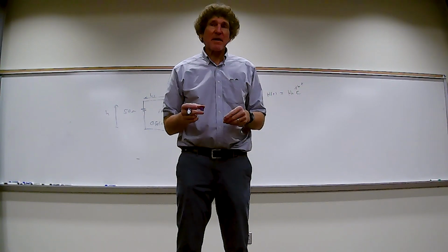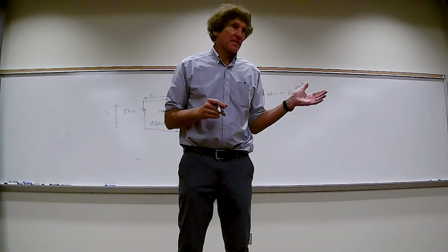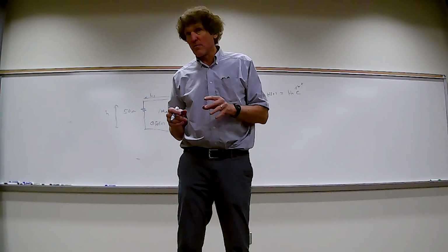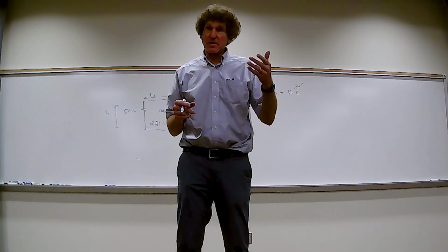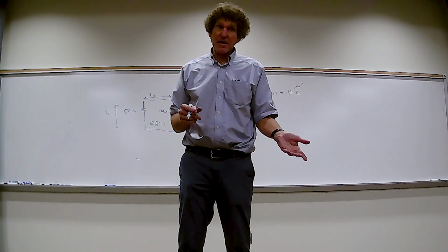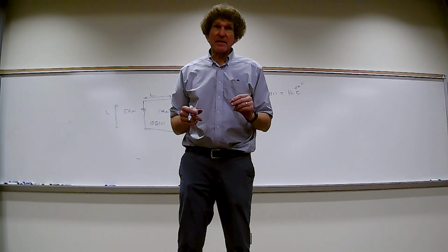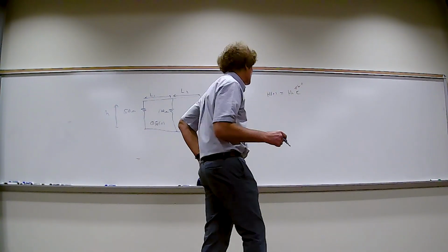He doesn't usually make you do that second part. He just wants magnitude and angle for a voltage or current, typically. Unfortunately, in the real world it's time varying, so what you would observe if you measured will be time varying. So you have to multiply the answers you get by e to the j omega t, and then take the real part of that. I'll go through this more with you. It probably rings bells.